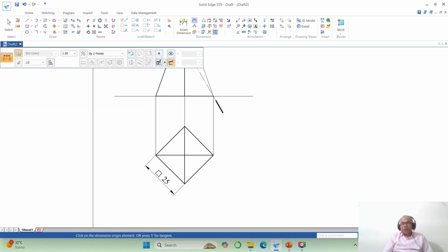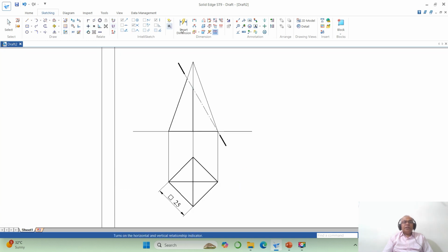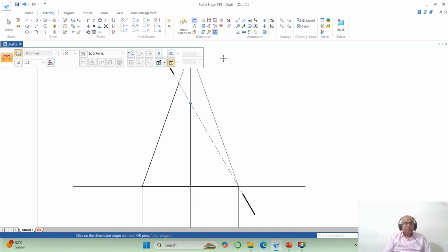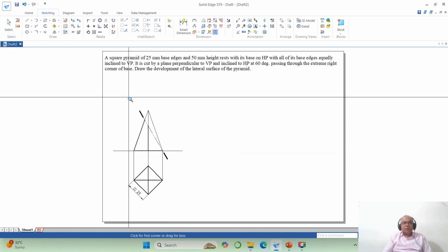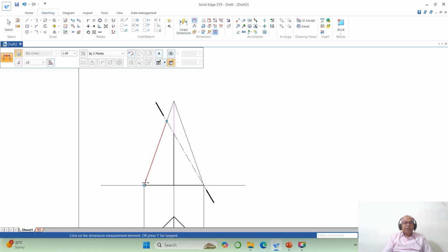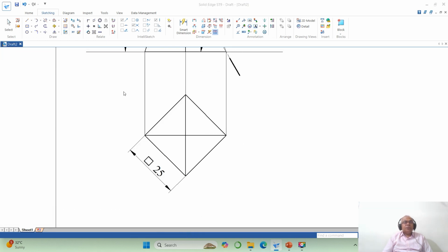OK now. Now you come down to this zoom window in the front view, go to distance between, select this end point, fit, go to this, go to distance between, select this point and this point, you make it horizontal or vertical and make it 50, and then you have the angle between this line and this line, you are going to get 60 degrees. Okay, now you go to top view.